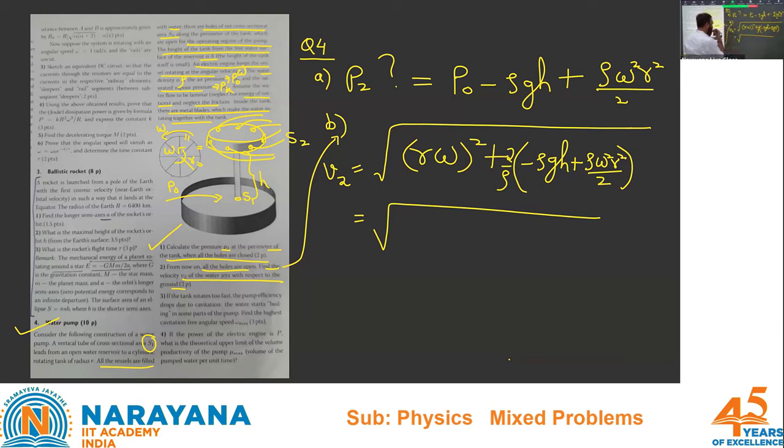So r square omega square term, and again r square. So it seems like 2 r square omega square minus 2 gh. That should be the answer for B part. Right? So when writing pressure, the rotating frame is fine, but when you are writing that velocity, you have to be careful. Now comes the more interesting part, C part.